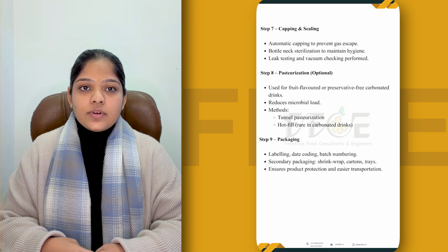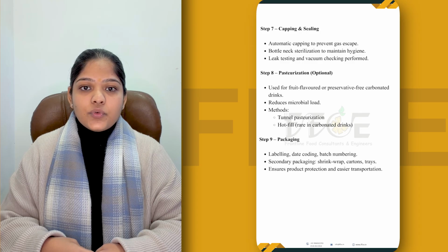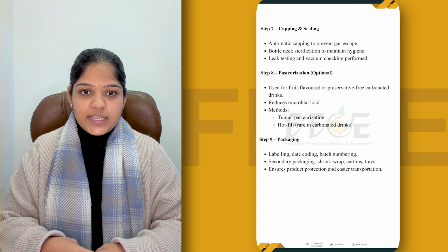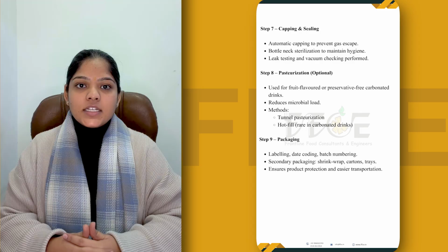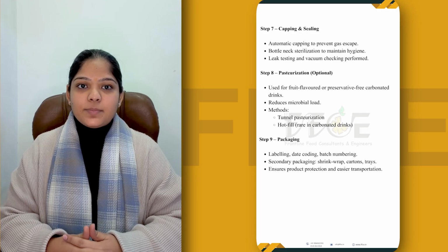Now we'll move forward to the eighth step, which is pasteurization, but it is optional. Pasteurization is mainly used for fruit-based or preservative-free carbonated drinks. It reduces microbial load and improves shelf life. Common methods include tunnel pasteurization, while hot fill is rarely used for carbonated beverages. So now we're discussing the last step, which is packaging.